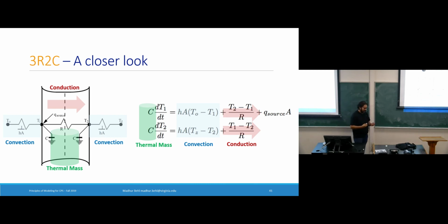And so this is the building block. This 3R2C network is the building block of creating a network now where every branch could be 3R2C corresponding to every surface of the zone, and collectively will result in a state space model for the zone. Okay? So we are getting close to our aha moment where everything will fall into place and you'll see this state space model in all its glory.